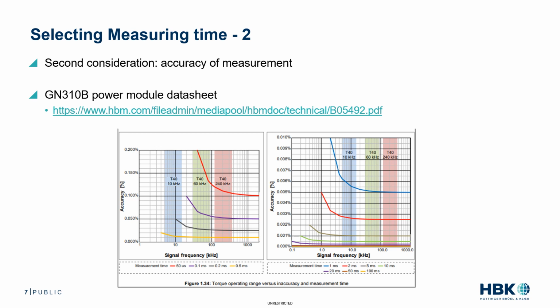The required accuracy of the measurement must also be considered. Timer accuracy is a trade-off between update rate and the minimum required accuracy. Accuracy increases as the measurement time increases. However, the update rate decreases as the measuring time increases, since the timer counter channel provides one torque result per measuring time. Thus, you get a less dynamic result as you increase the accuracy of the measurement.